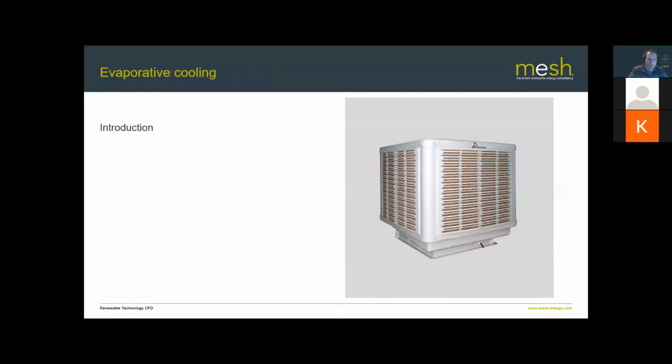So that's what an evaporative cooler looks like. Basically, the way it works is when water evaporates, it absorbs energy. So there's energy absorbed by water as it changes from liquid water into the vapor phase. The way to think about that is if you boil a kettle, the kettle will reach boiling point and sit at boiling point, and you're still putting heat into that kettle.